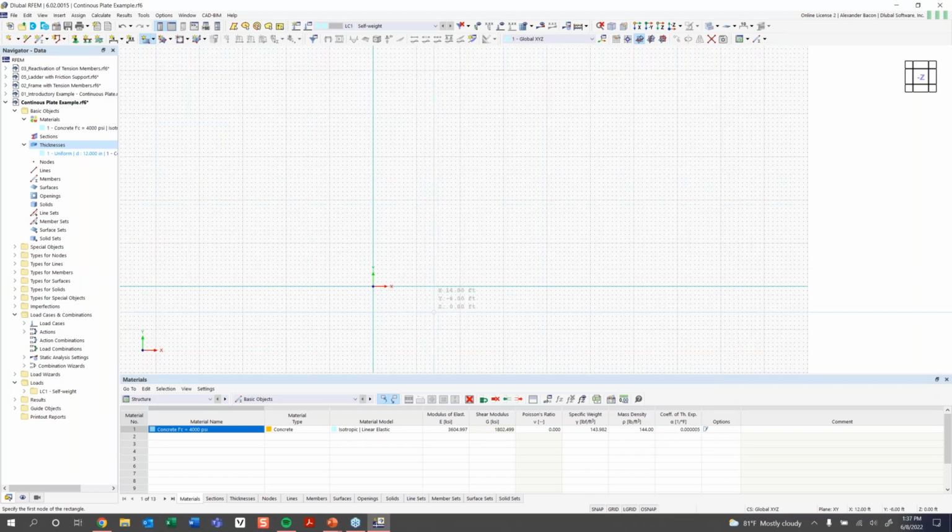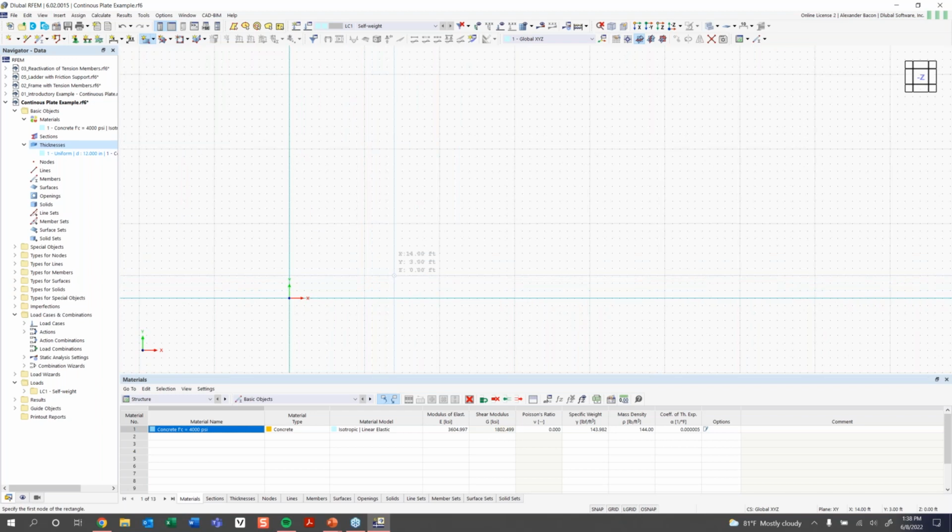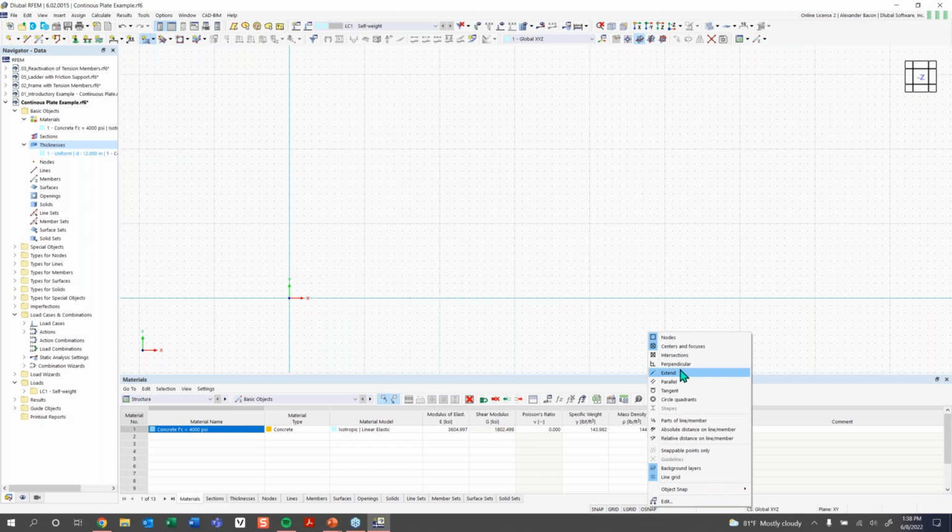And so once we click OK through all those boxes here, now you can see my cursor has changed to this reticle. And you can see that I am snapping to each one of these grid points here. So this will help me draw to the exact dimension to 1 foot the surface. You can also turn off the snap settings down here with this button. So you can turn those off and on. And you can right click here and see all of the different snap options. And this is similar to AutoCAD in a sense.